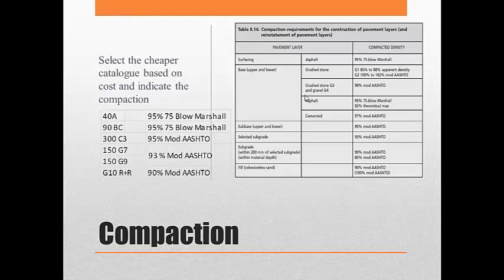Material property strength is strongly dependent on the compaction achieved in the field. The minimum compaction standards are presented in Table 8.14. It is important for this design to be acknowledged in the calculation context.